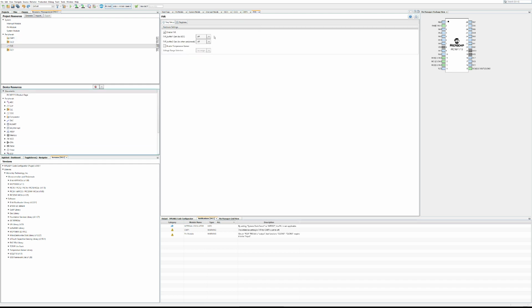The fixed voltage reference part internally outputs a 1.024 volt reference. You can then choose to multiply it by 2 or 4 to give you a 2.048 volt or 4.096 volt reference. And yeah, it can have different amounts of gain to the analog to digital converter versus to the comparators and other sensors. So that lets you define your threshold for the comparator in software. So you can say, bang, there, 4.096 volts. This one will have the positive input as CN0 and the negative input as fixed voltage reference.